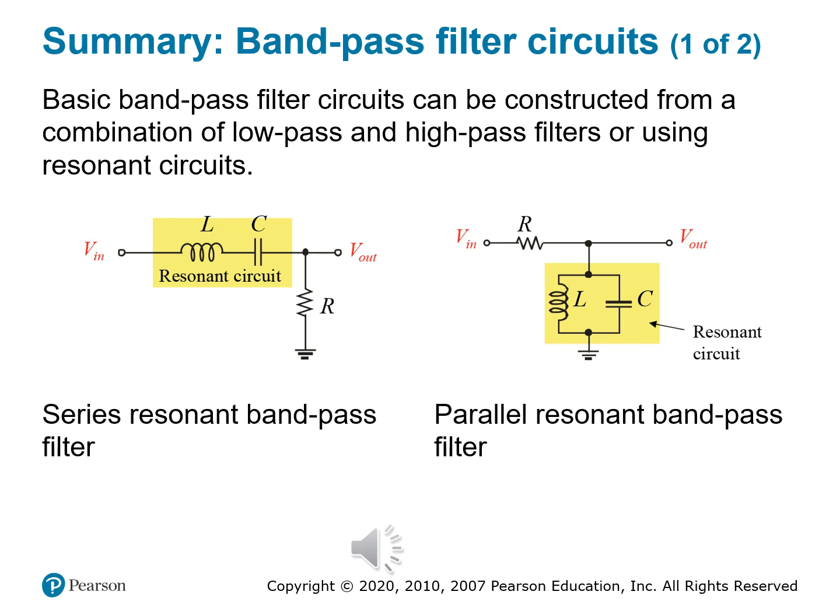If you look at the parallel resonant bandpass filter, you flip that structure, and now the LC combo is in parallel with the output. Off resonance, this tank circuit draws current away and attenuates out of band signals, but at the resonant point, it acts like an open circuit, allowing the signal to pass cleanly.